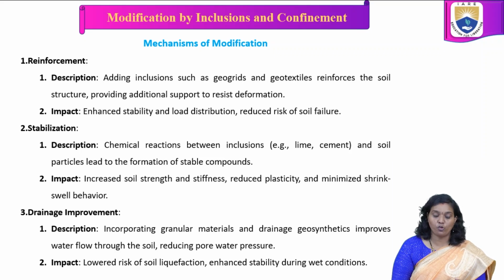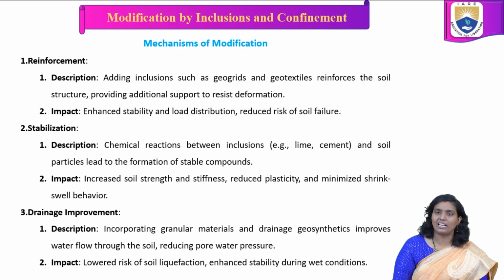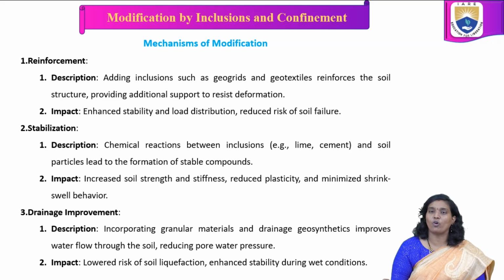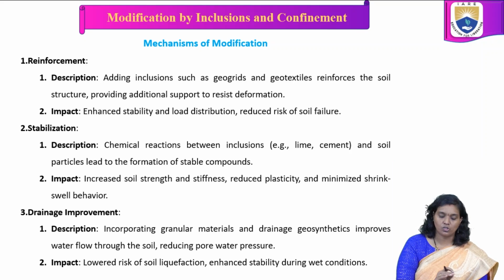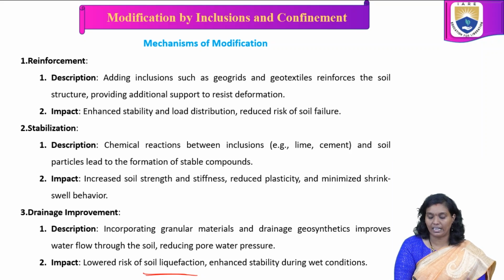In drainage improvement, incorporating granular materials and drainage geosynthetics improves water flow through the soil, reducing pore water pressure. As an impact of this mechanism of modification, it lowers the soil liquefaction risk and enhances stability during wet conditions.